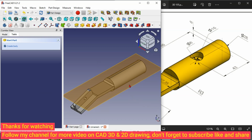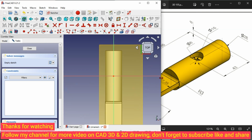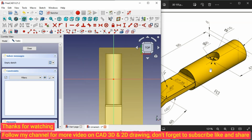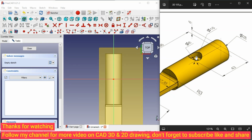Okay, click this datum, click sketch. You guys notice that our reference has changed from here to here because we clicked on this cylinder, so our reference will be for this cylinder only. Because the length is 86, the reference will be in the middle of the cylinder, 86 divided by 2 is 43. So this hole locates on the middle of the cylinder, so the dimension will be 43. We can use this reference point here to draw our hole, our pocket.